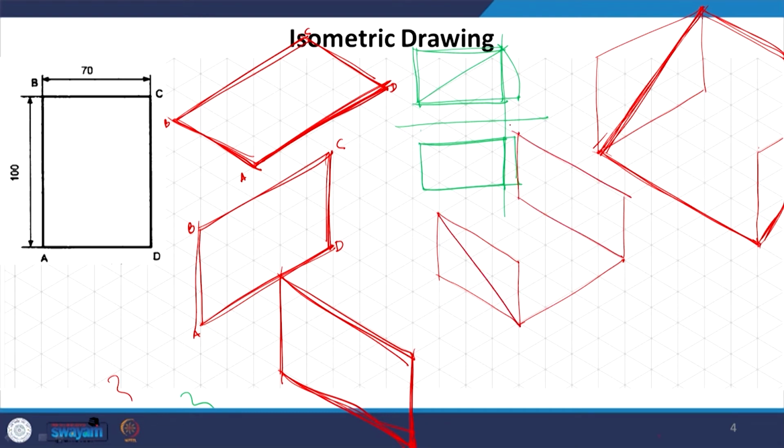Now you can see that I made a mistake and I immediately realized it because the line is not going to be parallel. The mistake that I committed was, here I measured say 3 units by 2 units. This is the reference rectangle which is helping us arrive at the non-isometric line, the slant. And here I took 4 and 2, and the moment I draw it, I can immediately see that this is not parallel to this.